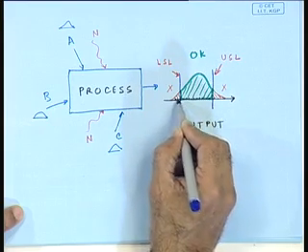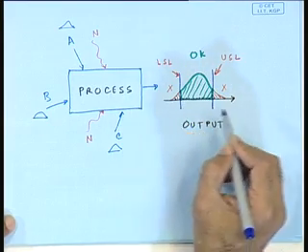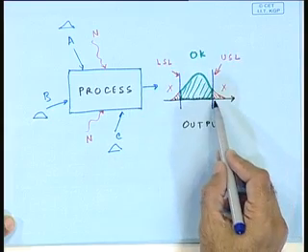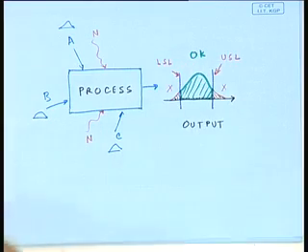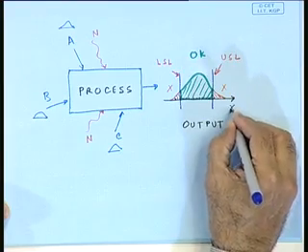And it turns out some of those are below the specification limit here on the lower side, and some are beyond the upper specification limit. But these are all individual measurements. I'm not talking about X bar. I'm not talking about R. I'm talking about raw X values. That's what I'm talking about. That's what I've plotted. In fact, that is the quantity that I need to measure in large numbers to try to see what the distribution looks like.